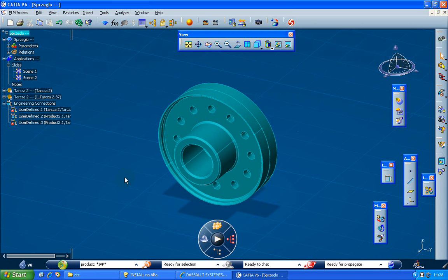you have defined a coincidence constraint in the assembly workbench. So it's a geometrical constraint, coincidence. You switch to DMU kinematics and you have to recreate the cylindrical joint. In V6, this is not necessary. You will not need to do that, because once you create this coincidence, CATIA V6 will understand that it's similar or equivalent to a cylindrical joint.